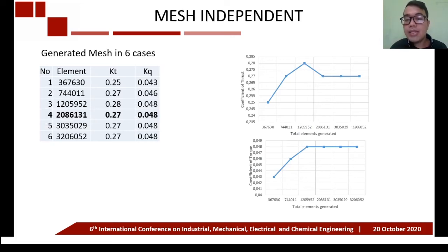This mesh independence study has been performed to ensure an adequate number of cells that is sufficient for all simulations to obtain accuracy and steadiness in the computational result, regardless of the longer CPU time. However, a total number of cells of about 2 million was selected for all simulations due to the reliability of the mesh result in capturing the flow field and pressure distribution on the blade surfaces.